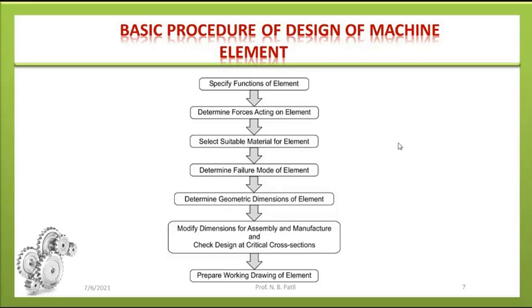Then inertia force due to change in linear or angular velocity. Then force set up during manufacturing of the part, resulting in residual stresses. Then the external force due to energy or torque transmitted by the machine part, which you can call a useful load. These are the different forces acting on the element, and you have to identify them first of all.